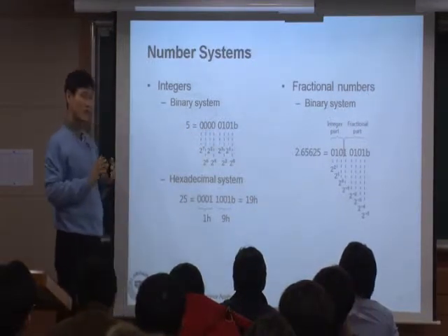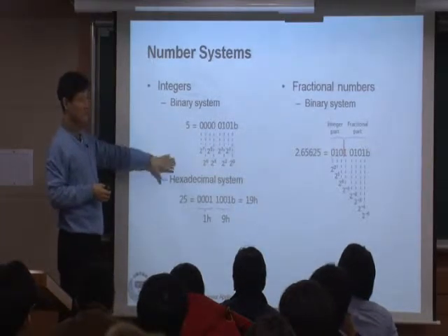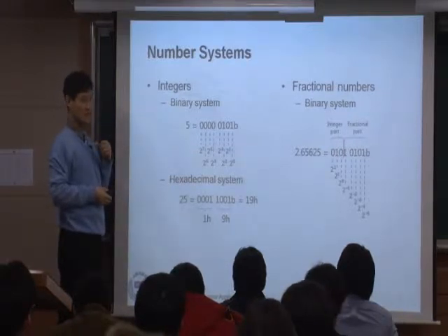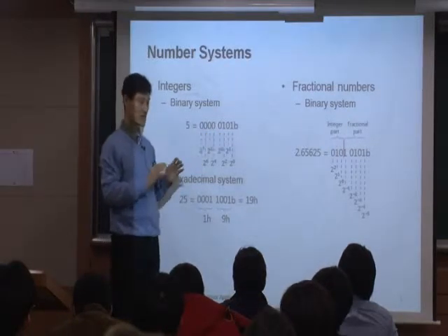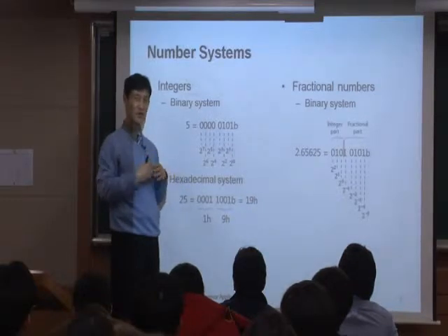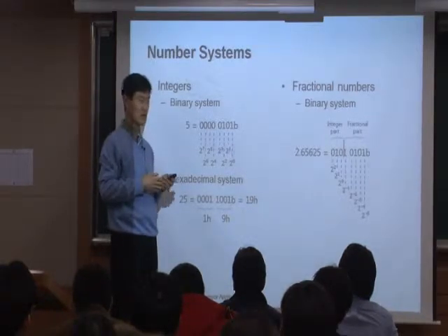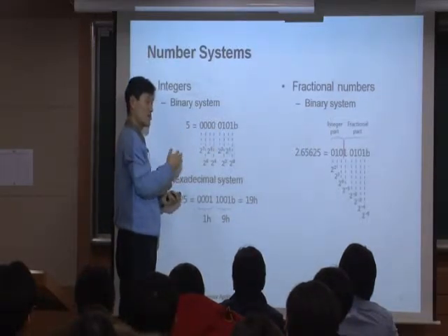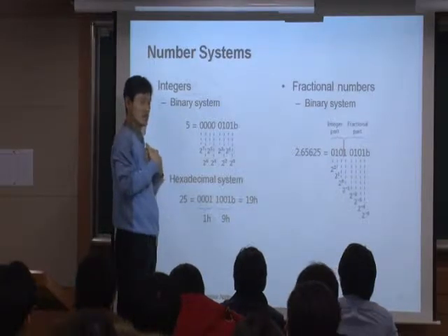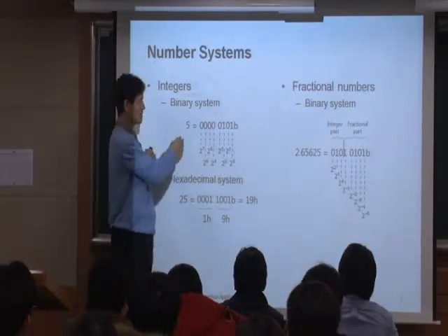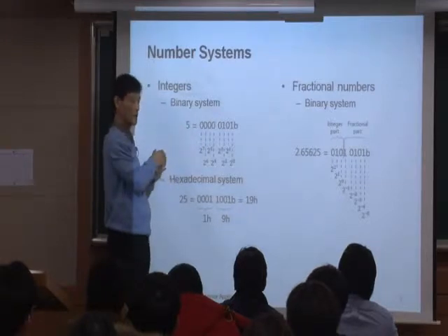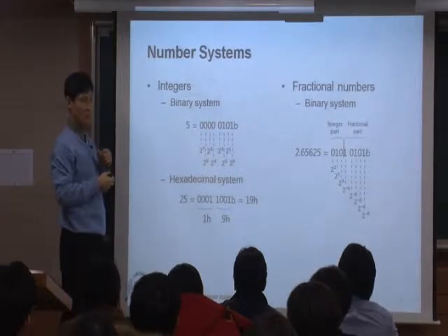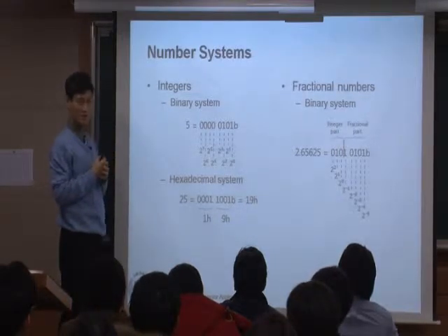But the microprocessor doesn't know whether it's 5 or 21 or 15H. That's how we read it. The microprocessor has 8 bits, that's it. You know what I'm saying? From the hardware and microprocessor perspective, they don't know how to read it. They have only 8 bits, and that's it. It's for us. We have to decide if we read these 8 bits as decimal, or as hexadecimal, or we just take it as binary. We decide that. You see my point?